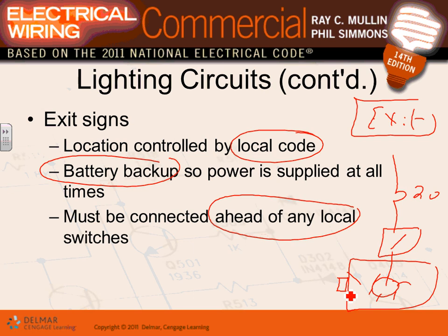Remember, there is a battery inside it. So what you do is you come from the line side of the switch and you feed it. Everybody see that? The exit sign has a battery, so you come from the line side of the switch and you feed it. It's the same thing as an emergency light. If you have those bug eyes that you're going to put here, you come from this side and you feed it.